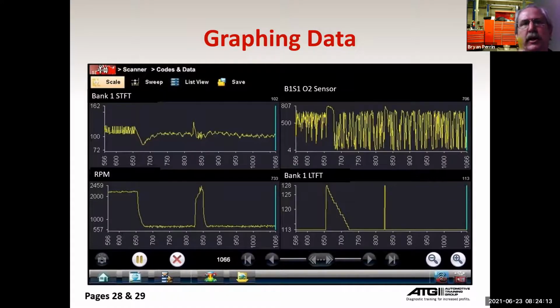So this is old GM, based on the computer numbering system of 255, because that's how many numbers you get out of one byte, and half of that is 128. So that's why this used 128, because again, this is old technology. We're really on base computer numbers. But our same rules apply. So 128 is 0. Anything below 128 is taking away injector on time. Anything above 128 is adding injector on time.